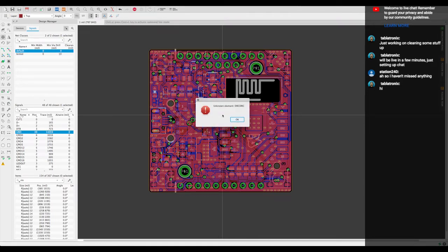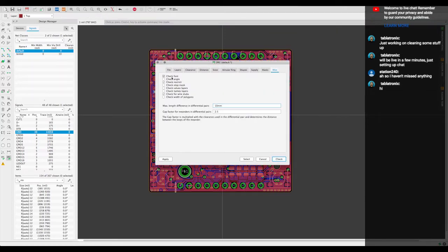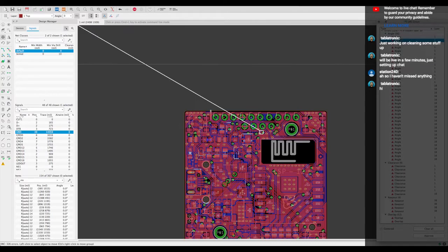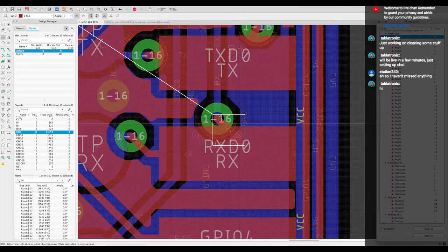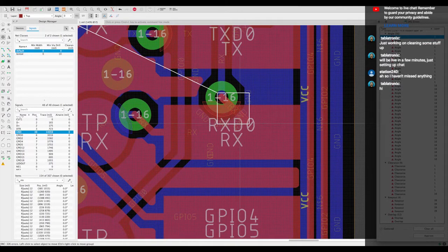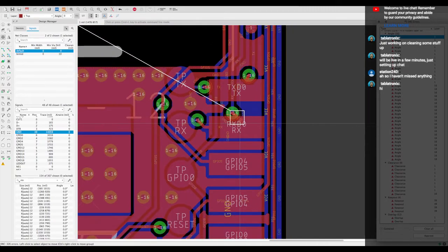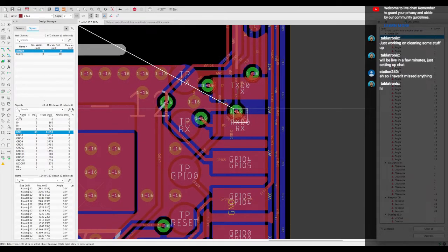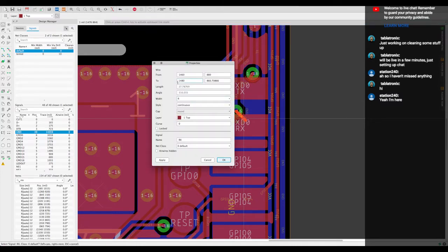Right now I was going to do a check angle on the DRC in Eagle. It'll give you angle violations. I don't know exactly what that means. I think if it's not 45 or 90 degree, it'll tell you. Of course, I don't know how you check the actual angle on it. I would think the info tool would give you the angle.